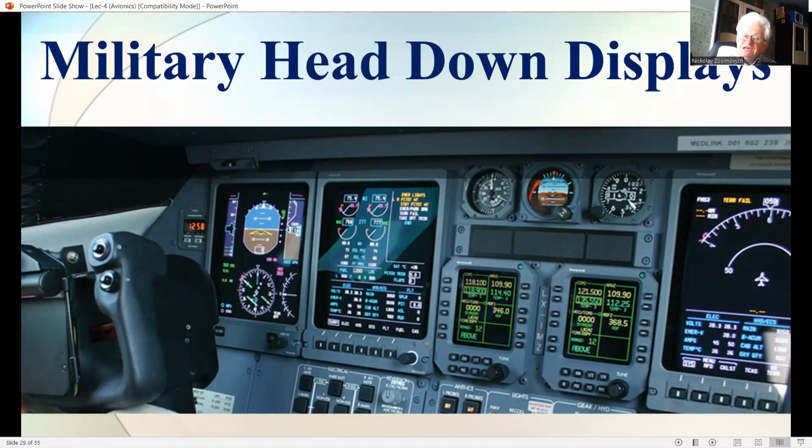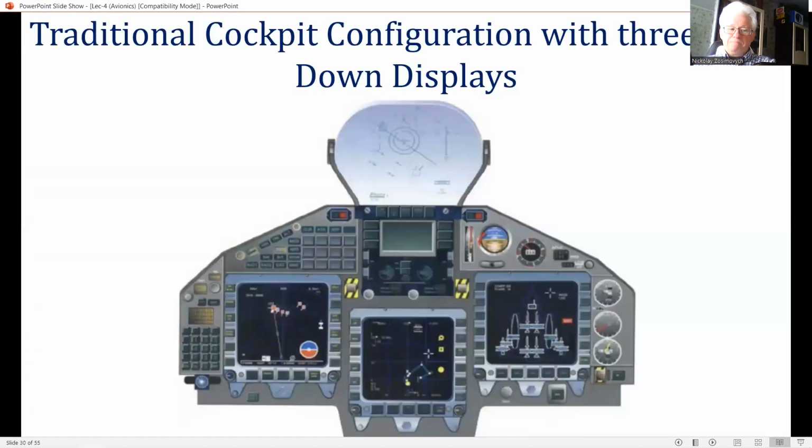Fuel and engine data, navigation waypoints, and a host of housekeeping functions like hydraulics and pressurization may be displayed. A stores management display is also required, showing the weapons carried and their status. It is usual to have a bezel around the display with keys. Sometimes key functions are dedicated, or they may be soft keys where the function is written beside the key on